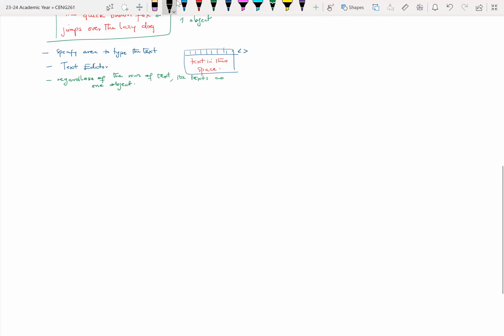just like how we have dimension style, we also need to do a text style. The text style has to do with how your text should appear. So we're also going to open a text style window, just like how we had the dimension style window.